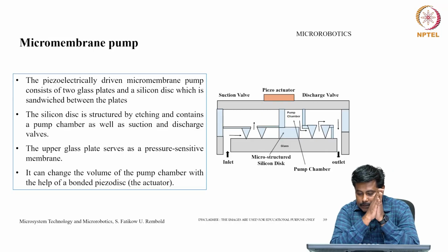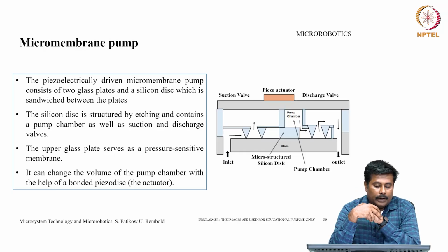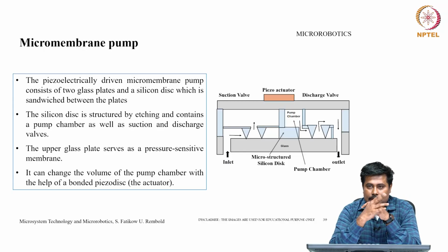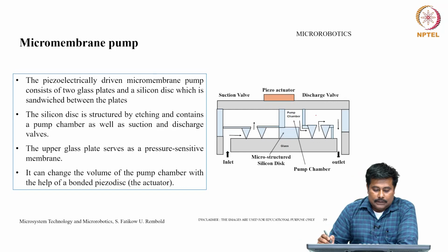This is one such pump, where the piezoelectric driven micromembrane pump consists of two glass plates and a silicon disc sandwiched between these two plates. Here the silicon disc is structured by etching and contains a pump chamber as well as suction and discharge valves. The upper glass plate serves as a pressure sensitive membrane. It can change the volume of the chamber with the help of a bonded piezo disc, which is nothing but an actuator.